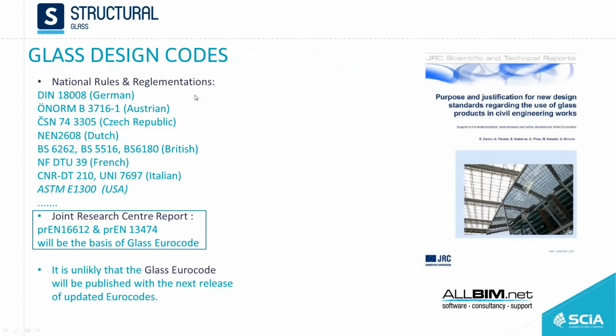There are many national rules and regulations, but mostly, as they say, there are rules. So there are a lot of proposed dimensions and a lot of conforming rules, so that the calculation of the glass can be avoided. This happens a lot in Germany, for instance. For glass balustrades, there's actually a table, and according to geometry, if you respect the maximum length, the maximum height, and some load conditions, you can go through a table and select. If you don't want to respect, or the architect forces you to go outside of those norms, then you have the formulas to calculate.